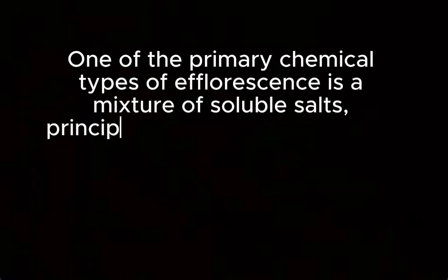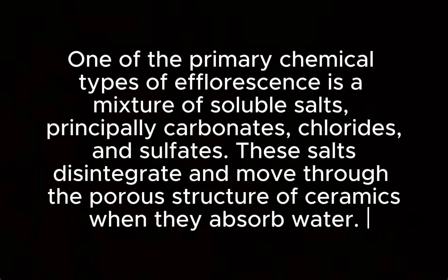One of the primary chemical types of efflorescence is a mixture of soluble salts, principally carbonates, chlorides, and sulfates. These salts dissolve and move through the porous structure of ceramics when they absorb water.